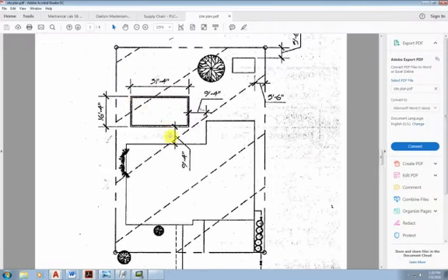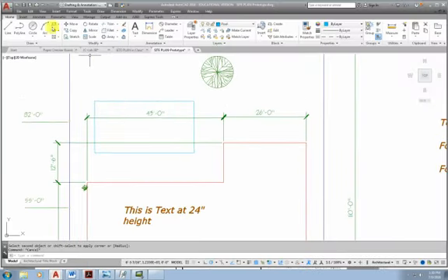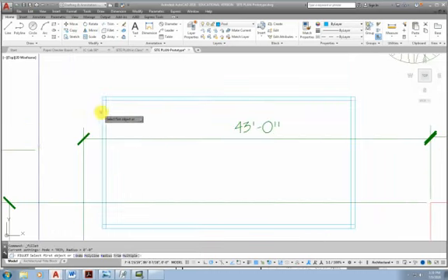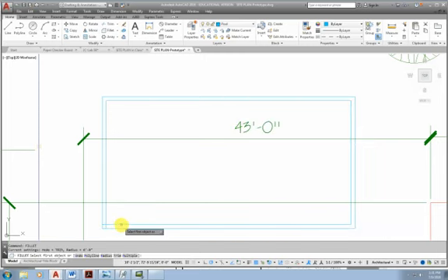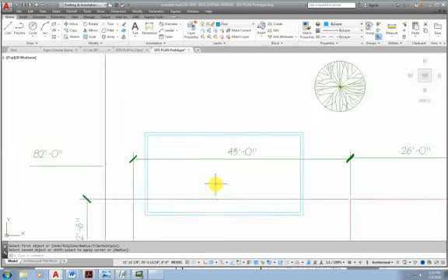And so let's see what 6 inches looks like on that. You'll find a lot of your architectural drawings don't have every dimension on it. And so we'll offset that 6. That looks good. Select the line, select the side, and then again we're going to trim up those lines with the fillet command in a radius of 0. And you can hit right mouse button to repeat the command or hit the space bar.